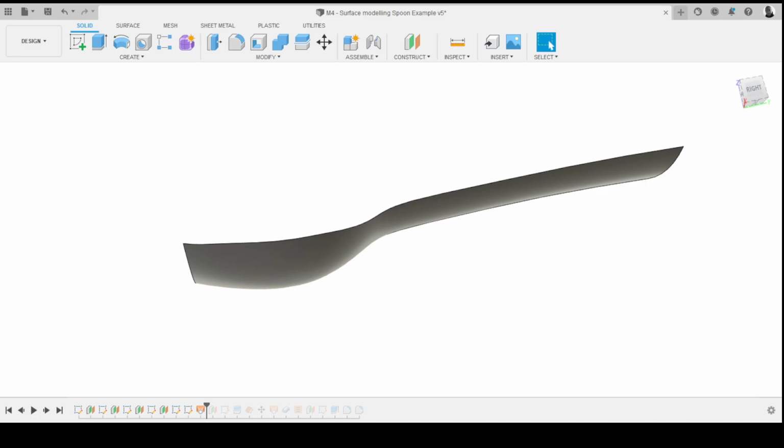For whatever reason, if we wanted a different shape at the top of that hammerhead handle, we might just do a quick surface loft or surface extrusion or something like that to create that shape and use that as the splitting tool. So those are the kind of use cases I find myself generally using it for. As I say, there are people that will spend all their time in surface modelling and will do complex car designs using overbuilding of surfaces and trimming them back. I'm not going to show you all that now because that's probably almost a course within itself, but I'm just going to show you the basics of how I think it's most practically used and how you can approach it.